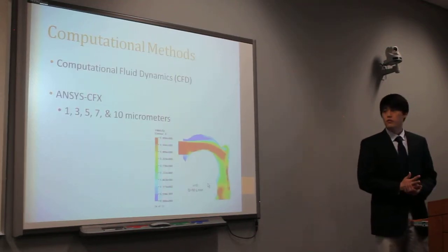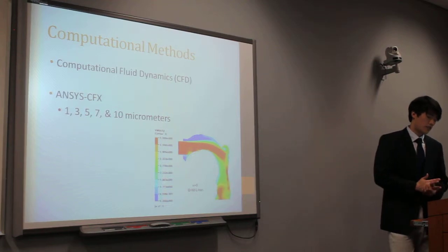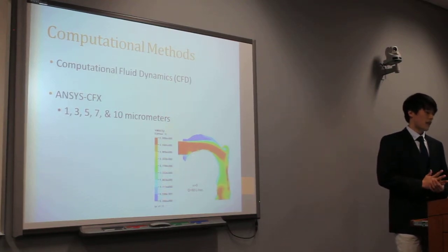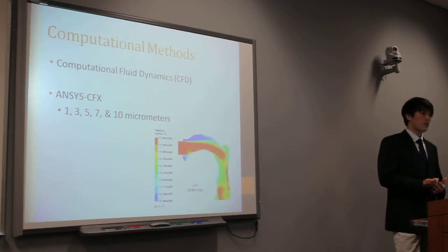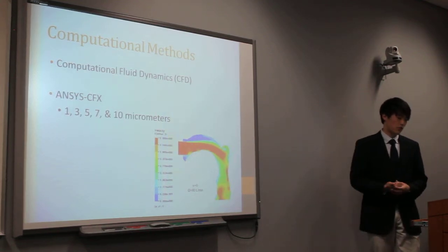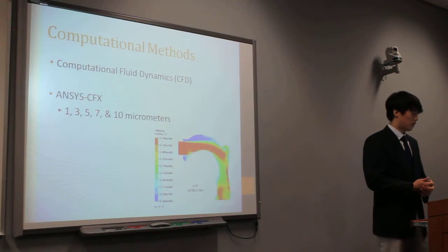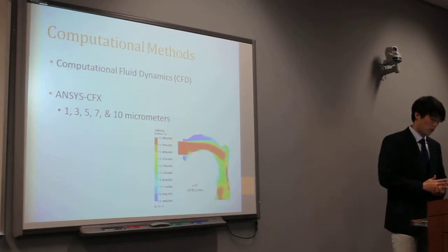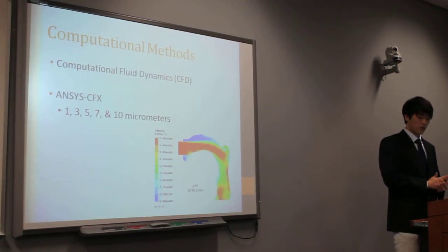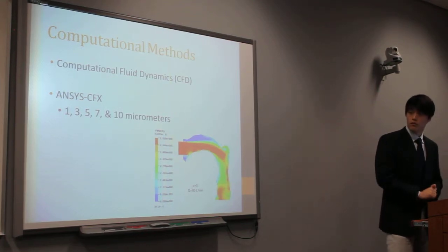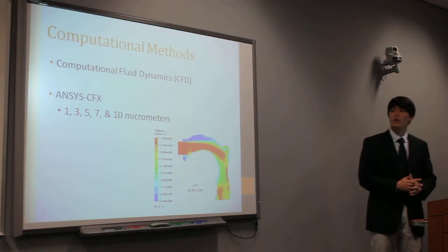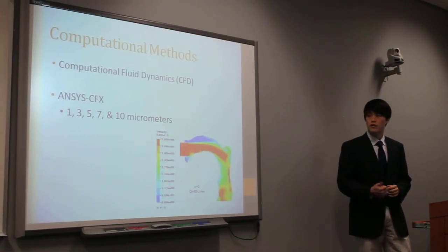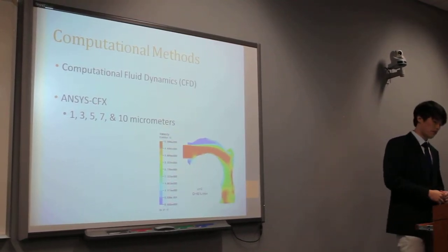For the computational fluid dynamics simulation, ANSYS CFX was used to calculate the airflow, aerosol transport, and aerosol deposition within the model. The exact same model was used, and for each flow condition, the transport and deposition of 5 different aerosol particles were studied, which are 1, 3, 5, 7, and 10 micrometers.